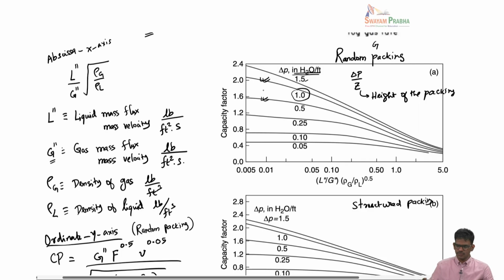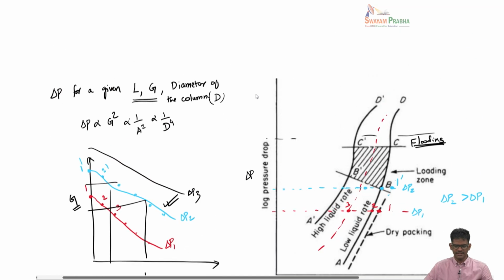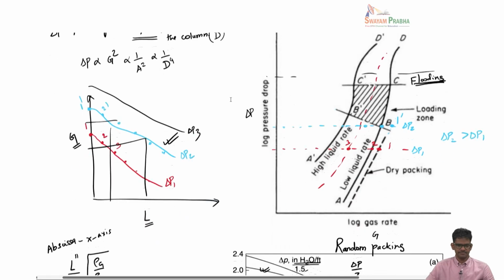So that's what I was trying to tell you before, that we will be able to give a target or desired pressure drop and then correspondingly get the diameter of the column. So far so good. What I am going to do now is illustrate this with an example of how to use this information and decide a column diameter for a given pressure drop, so that the use of this information will become more evident.